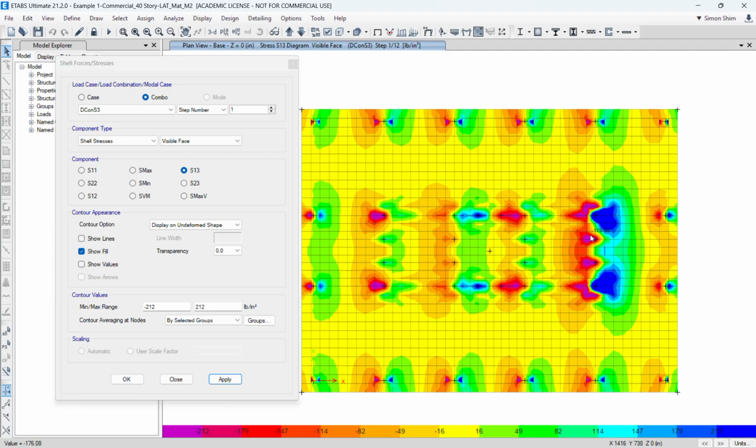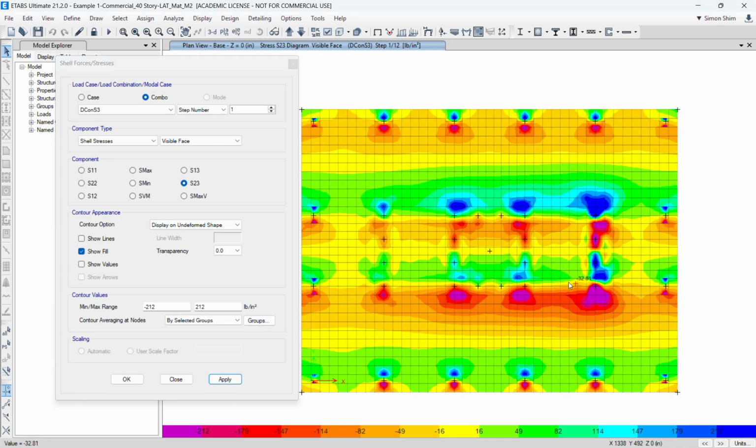Because wind and gravity effects are summed up and cumulative, causing some high shear stress. Then you need to look at this 3D model. We have the sign convention X and Y. So for shear stress, you need to consider both S13 and S23 directions.